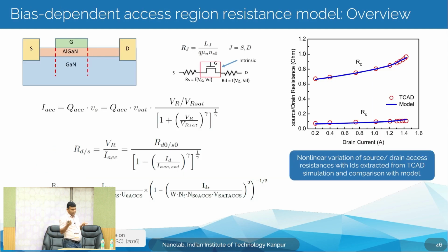The excess region is very important, and here it sees a good amount of electric field which causes velocity saturation. This has been modeled as a nonlinear function of current. Recently we worked on improving this model and published a work where we found a problem with the current based descriptions, and now we have moved to a voltage based description of the excess region. So, that is the modeling of velocity saturation. This especially causes a problem in the transient simulation.